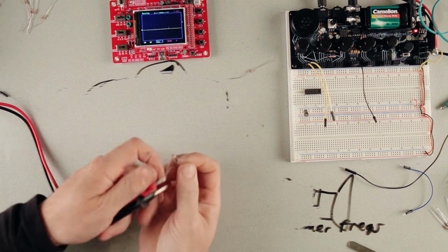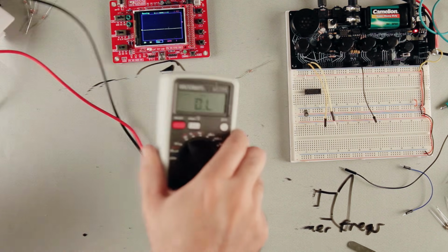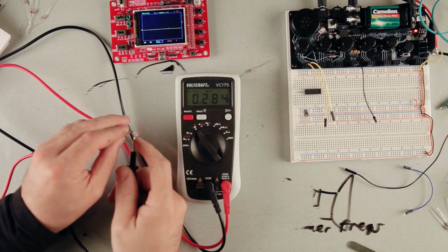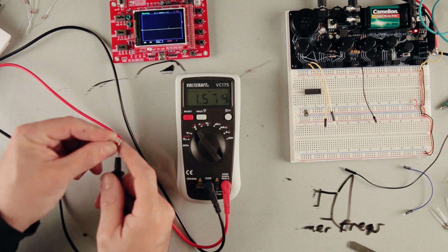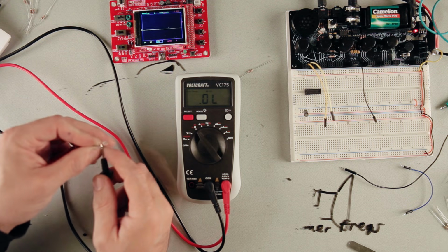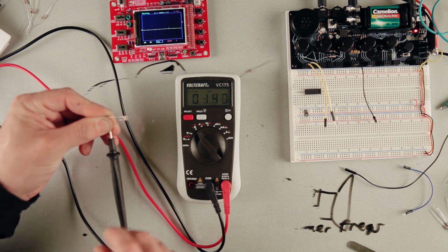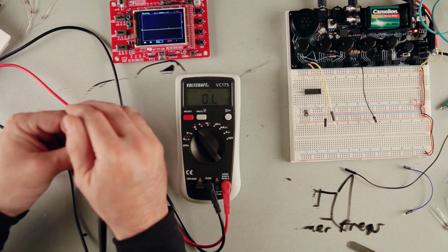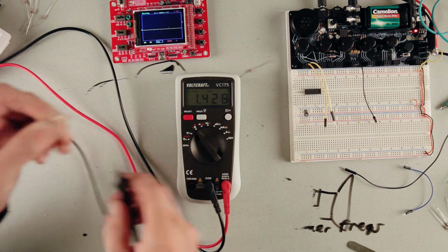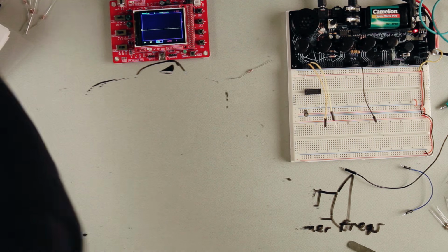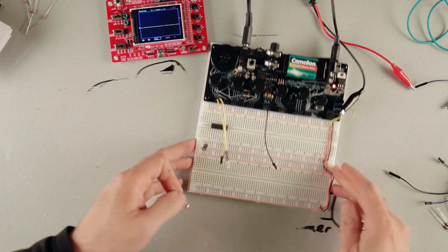So we've got this light sensor here, and got my meter, and we hold it up here, and you can see that there's 1,500. Oops. Hard to hold. Okay, so it changes with the light. So now it's 5,000, there's more light on it, and it'll be 1,500 ohms. So these are all things that we can change the resistance, which will change the pitch. So what we're going to do now is we're going to play with those different possibilities.